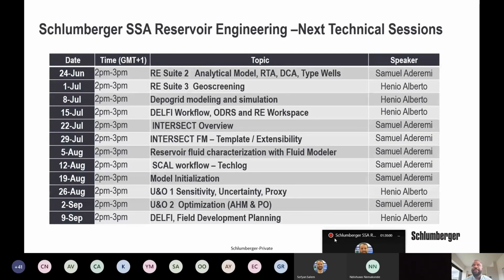Now, if you have an aquifer model in Petrel, for example, you are not able to automatically drag that aquifer to your material balance yet. This is something that is being worked on, but you can input the main parameters, whether it's a Fetkovich or linear aquifer, for example. You can input the same parameters to replicate the same aquifer influx response and pressure support to your reservoir.